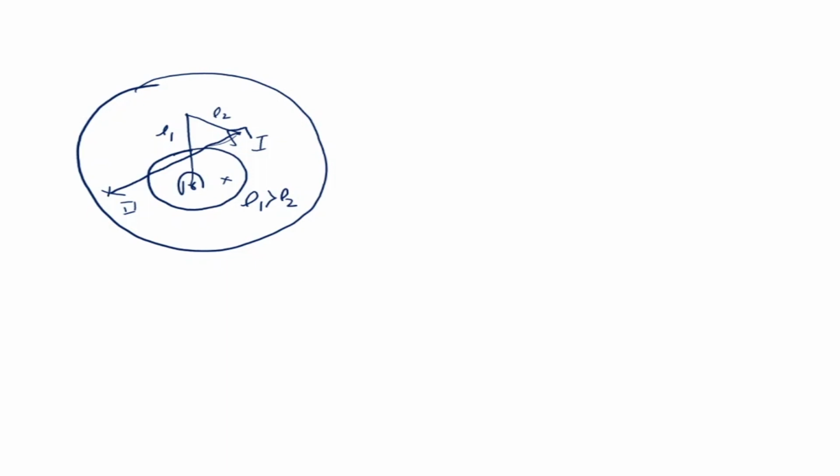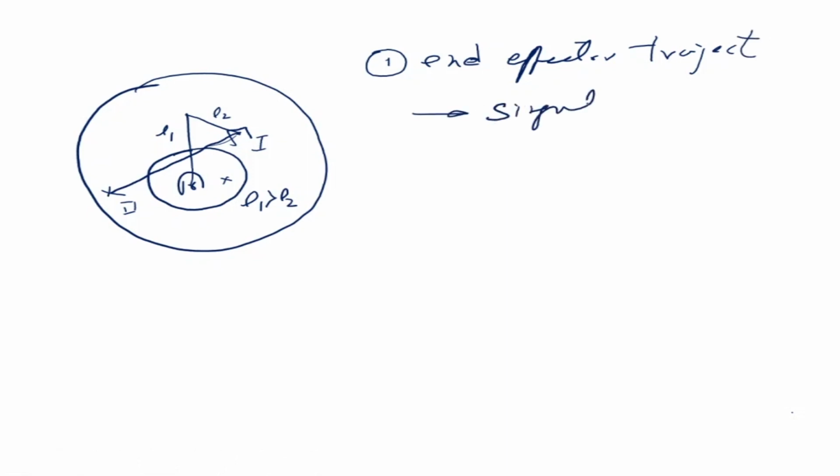So this is basically showing that if you plan at the end effector level, at the end effector trajectory, it may go and get into a singular position. It may go into a singularity. Now this would mean that you are only giving the start point and the end point. You're not interested in what is happening in between, right? And you cannot compute singularities, and you're not expected to know where a singularity is. So if in terms of planning, you simply plan the path and say from this point to this point it has to go, it could be going in such a way that it goes through a singularity, and this is going to be a problem.